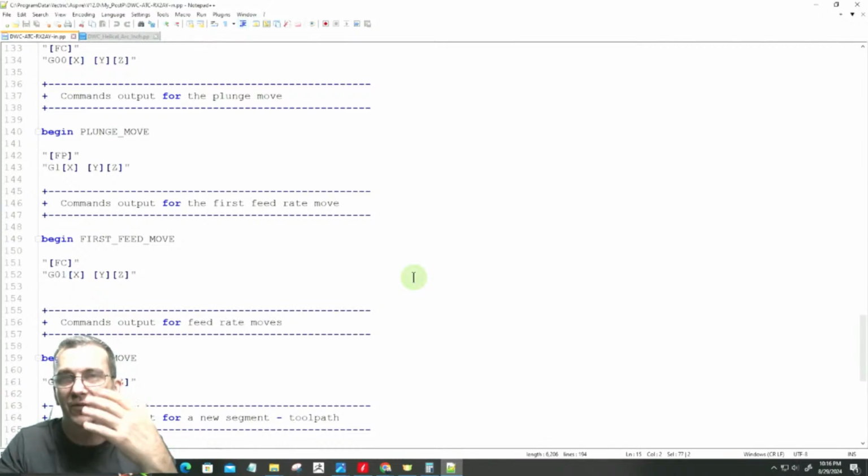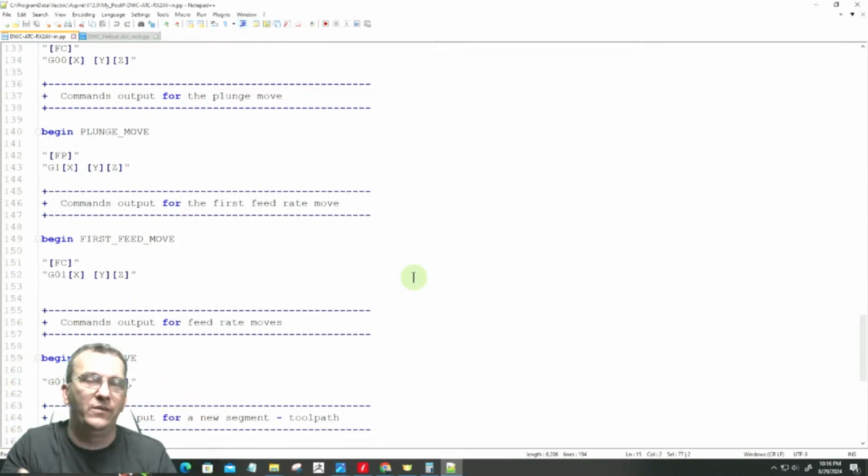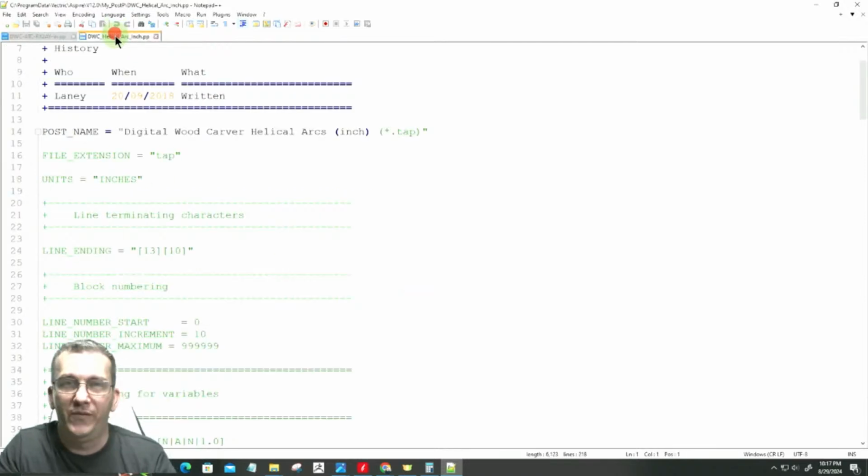as long as you're using the right post processor. So if you're just getting the fourth axis, you need to make sure you check with your manufacturer. Is there a particular rotary post processor that I should be using with my machine? If so, where do I access it? Usually Vectric has a whole list of different machines and their post processors, or it's provided when you purchase your machine, or you can download it from your manufacturer's website.